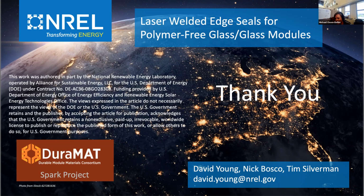And another anonymous question here. What's the required overlap between the welds in order to get a hermetic seal? Well, you saw that the width of the weld, at least in one of the cross-sectional images that I showed, was like 25 microns wide. So you'd probably want to overlap that, maybe a third or half, in order to get the seal.